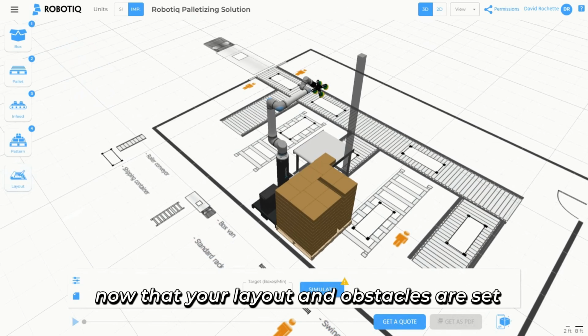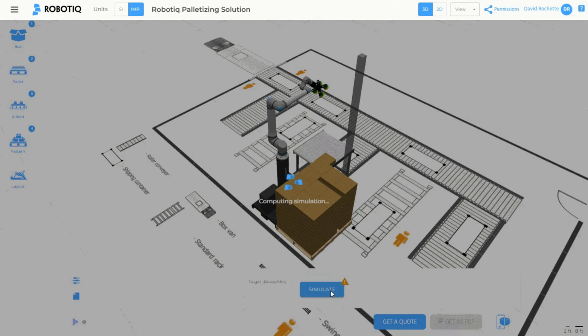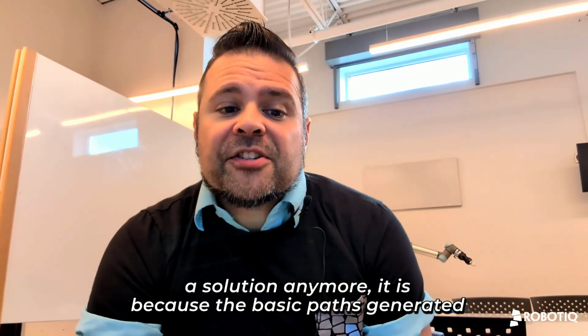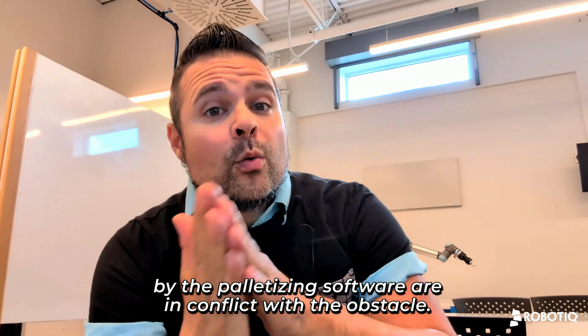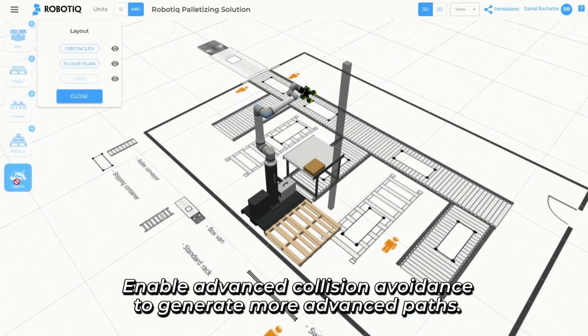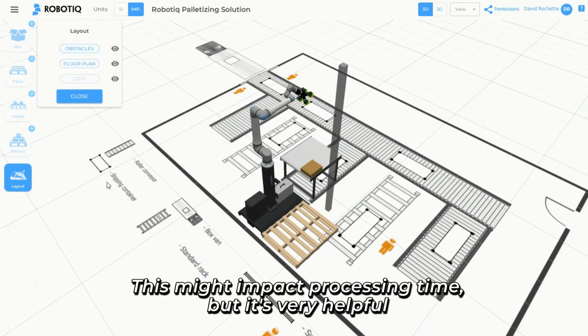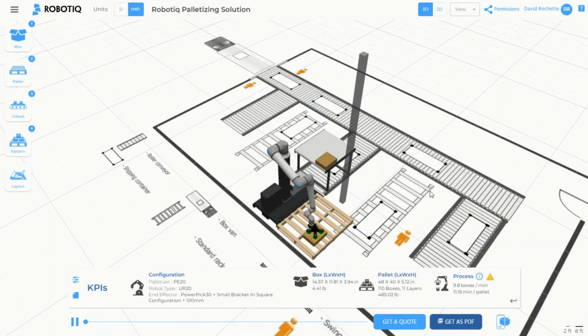Now that your layout and obstacles are set, click Simulate to preview how your robot will navigate the environment. If, after creating the obstacle, the simulator cannot find a solution anymore, it is because the basic paths generated by the palletizing software are in conflict with the obstacle. Enable advanced collision avoidance to generate more advanced paths. This might impact processing time, but it's very helpful when navigating through tighter clearances.